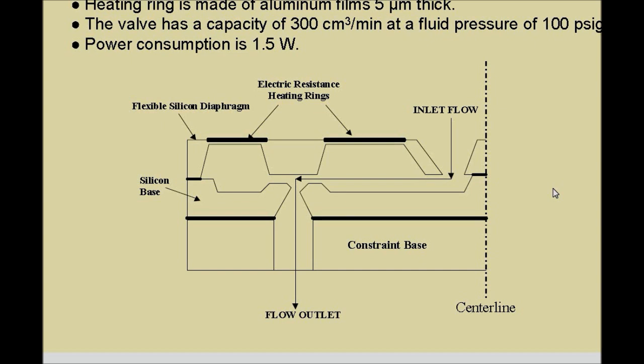Well, these micro valves again operate on the principle of micro actuation, and here is a design. In this figure, you are going to use the heating of two electrical rings, resistor rings, that are attached to the top of the diaphragm. You can see here these two dark things form the resistor rings, and this is the diaphragm.